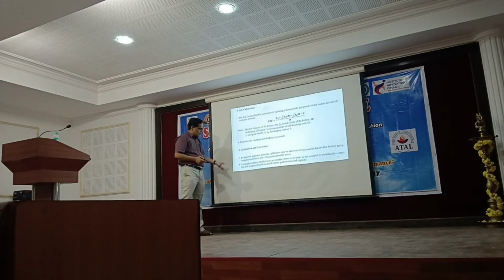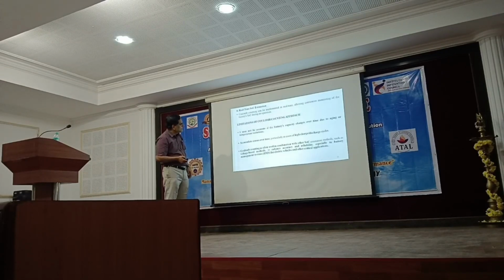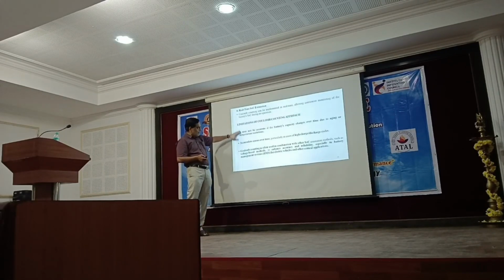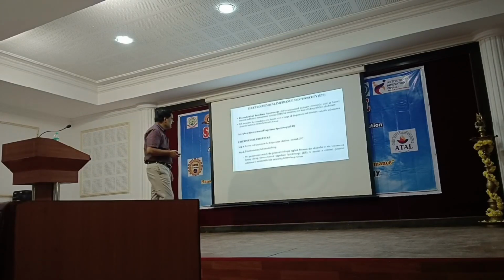And again, you do calibration also. I mentioned Kalman filtering. It's all signal processing. And again, coulomb counting also, if we have some limitation, that's why we try to bring in Kalman filtering to make it much more precise when you go for SOC estimation.